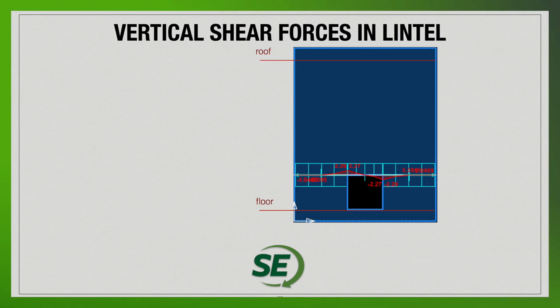We can then also look at the forces for the lintel area. We can see what the shear forces are going to be for the area just above the opening. Here you can see I included the entire strip to each side of the opening as well. You can kind of see that force flowing through those elements, but you can see that shear is spiking at the edges of the opening.